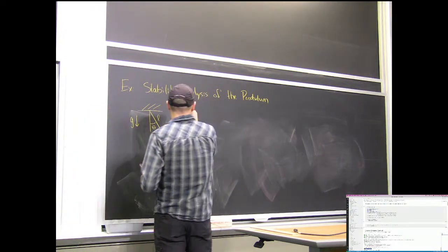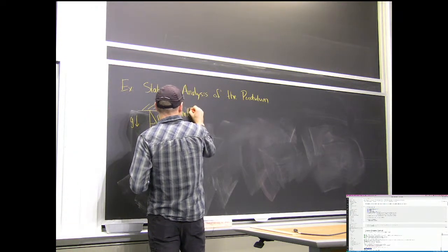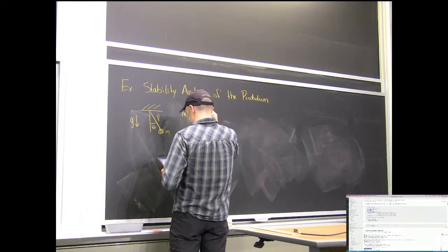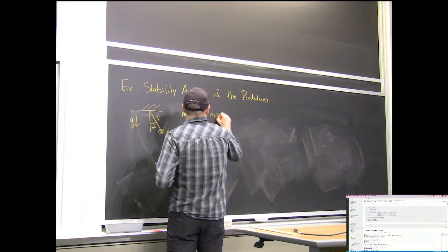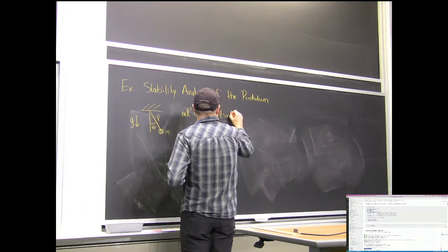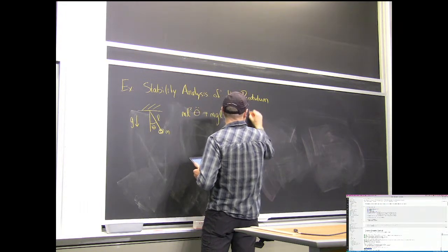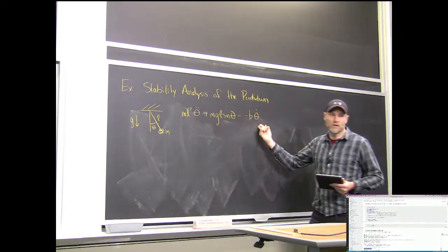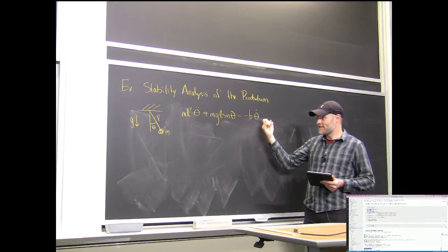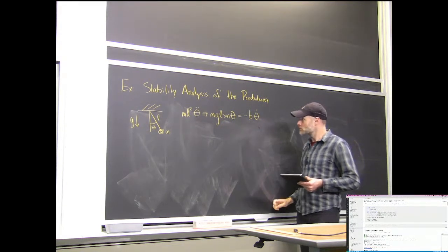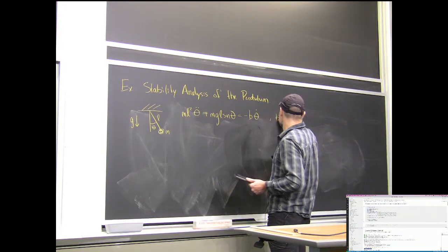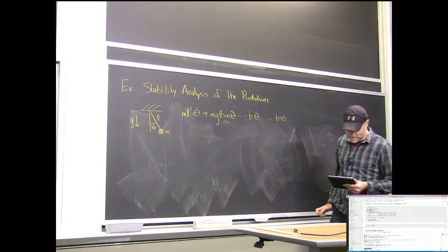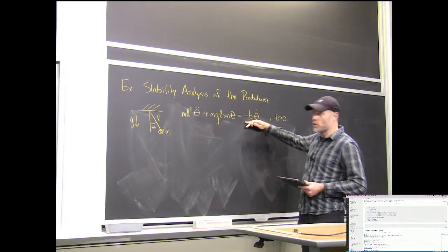Okay, so if I think of the damped pendulum here, my equations of motion, I'm going to write them slightly differently today. The friction term, the damping term, I'm going to go ahead and write over on the right-hand side as if it's a force coming in. I want my damping to be positive if I'm going to expect this thing to be stable. So think of this as joint friction, right?